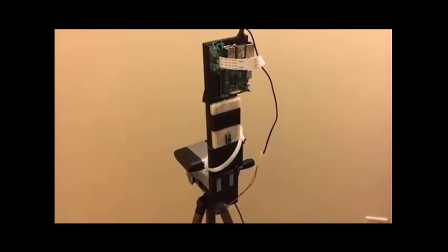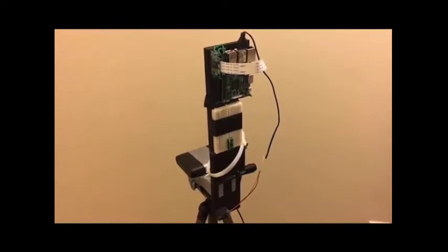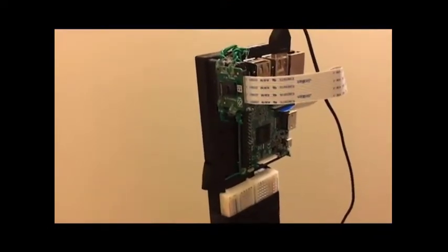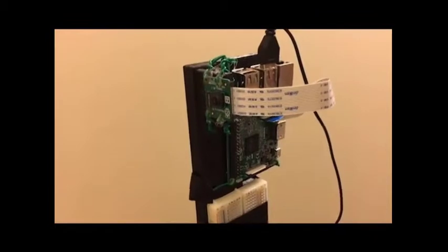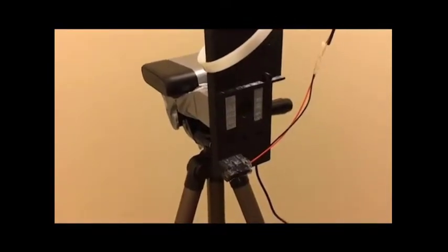The LiDAR system is designed around computer vision and tracking algorithms, and geometric relations are used to determine range measurements. The transmitter of the system is the red line laser, as seen here, and the receiver of the system is the Raspberry Pi camera. The receiver collects and detects return photons while minimizing background noise, while the transmitter provides laser pulses that emit photons.